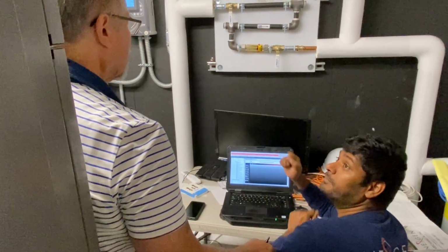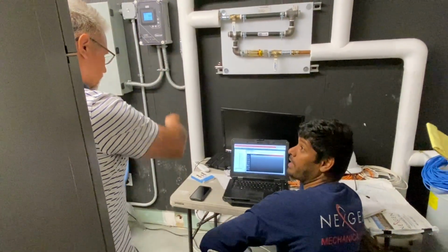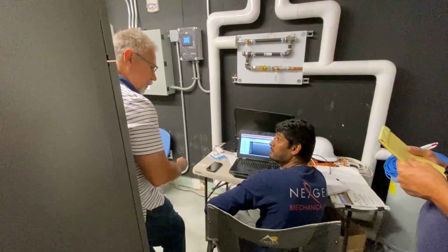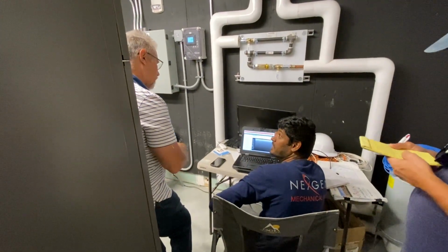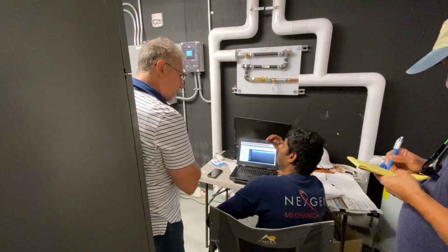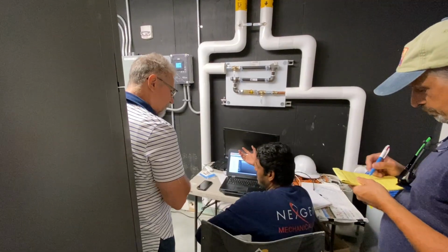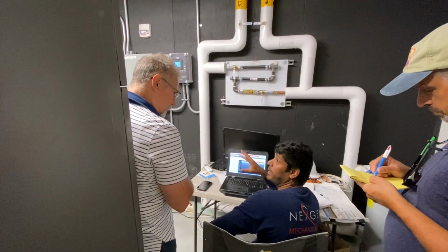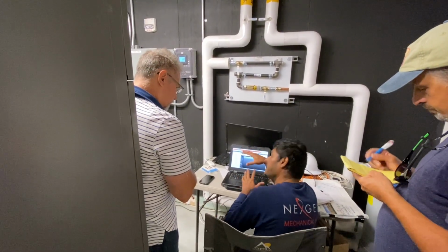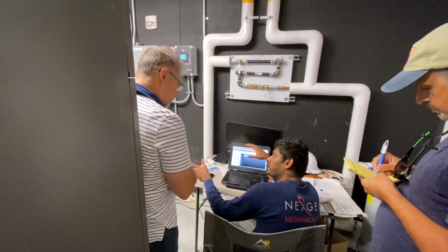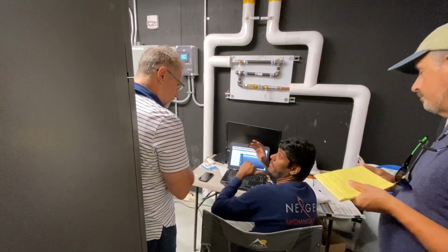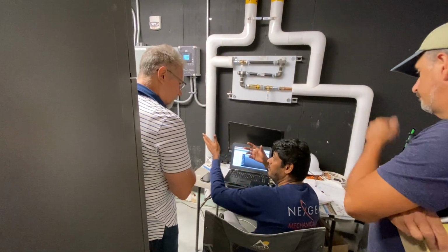Okay. So what about, I'm occupied in the morning, I'm going to lunch. The occupancy system says there's nobody in the room. What does it do? Standby. That is also adjustable from the graphic. For example, let's say my occupied set point, according to the sequence they asked for, is 74 for cooling. So 74 is my cooling set point. During occupied, when my motion is also detected, I want to achieve 74. If it goes more than 74, I open my damper to cool max, or modulate to cool max according to the demand.